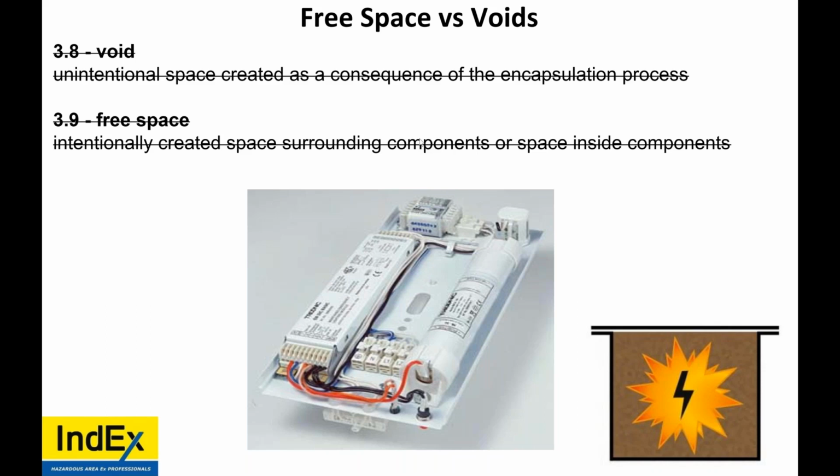So what they're doing is they're producing the same piece of equipment, but it would have different power levels, different temperatures. So if you have an MA device that is rated EPL GB, it can only be installed in a zone 1 or 2. Always follow what the EPL says, the equipment protection level. ABC, zone 0, 1, 2. DA, DB, DC, 20, 21, 22.